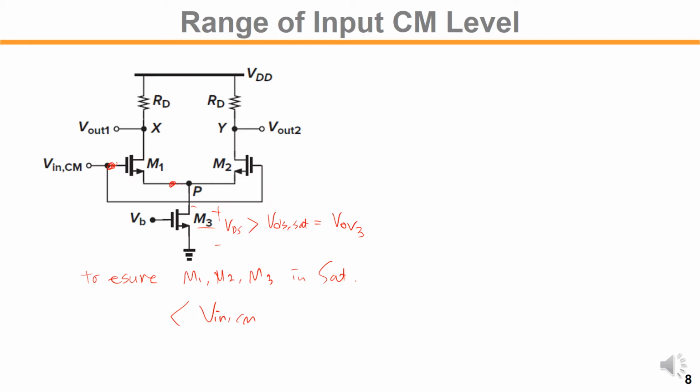And also for that case, the current is flowing equally through both branches, M1 and M2, so that will give us VGS, which is Vth plus overdrive 1, right? So overdrive 1 and overdrive 2 are the same. So the minimum input voltage will be what? Starting from Voverdrive3 plus 1 VGS. And the VGS is VTH plus Voverdrive1, right? That would be the minimum input voltage.